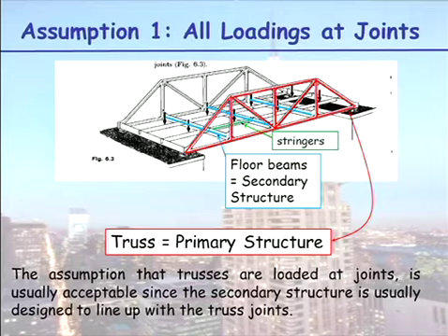And thus, when you consider loading on your decking in between the 2 trusses, if you consider a load path, if you consider a point load as shown here, that load transfers into this white member, then into these blue members, then into the truss member, and then into the supports. So the load path would be, well, hang on, I'll put a load here on this stringer. So here we have a load in the stringer there.